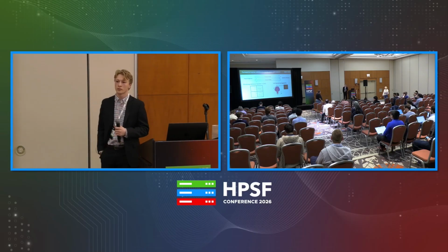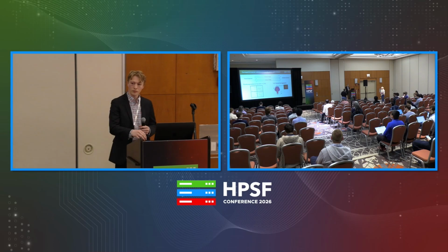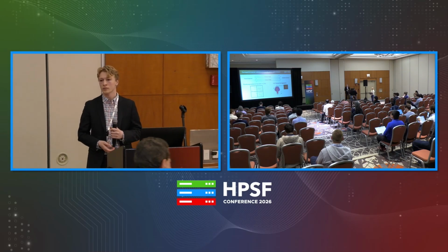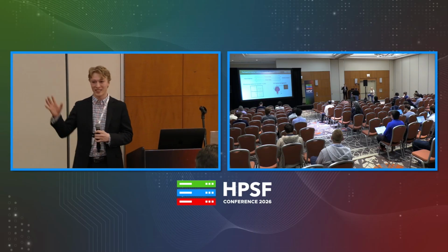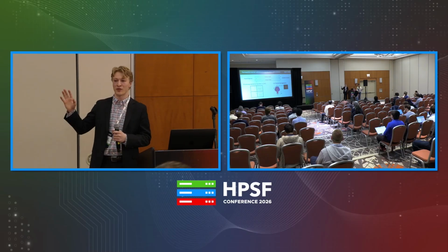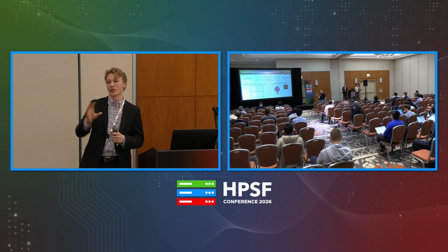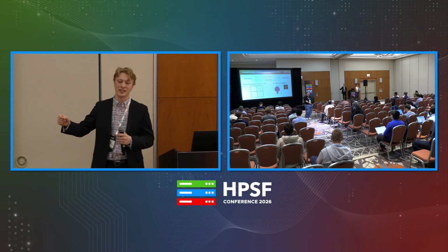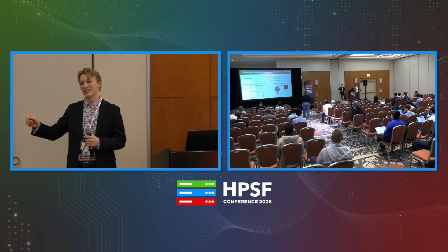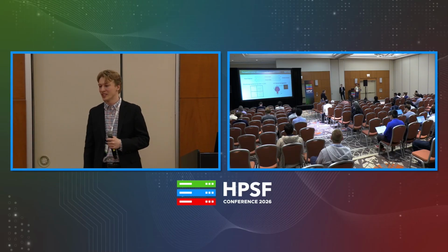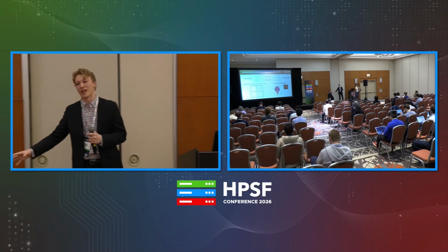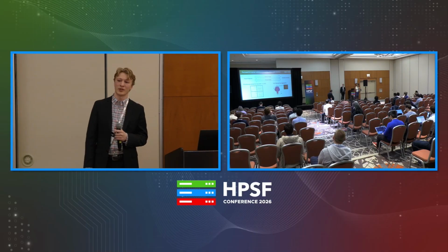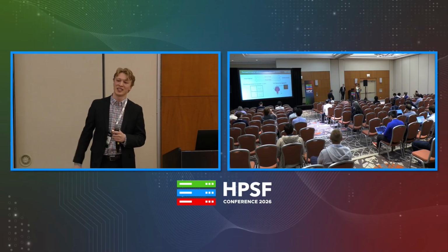I have a question about your build system. Since you're coupling Kokkos and OpenFOAM, ArborX, and probably PyTorch, what does your build system look like? That's a good question. I had to write a lot of my own build system. I just wrote a big bash file that goes through and compiles OpenFOAM, the solver, and then couples it to Kokkos and calls CMake and does all the steps. And then for the PyTorch part, I had to use PyBind. So I had the initial part with the compilation with OpenFOAM and Kokkos, and then I wrapped that into a PyTorch layer. So it really is just kind of one big bash layer hack.